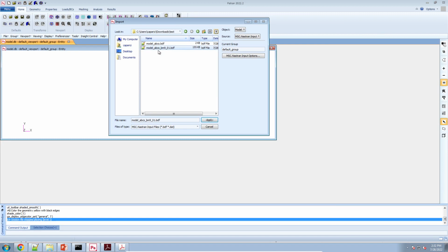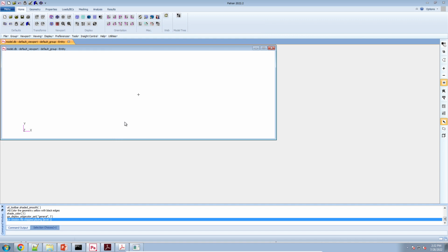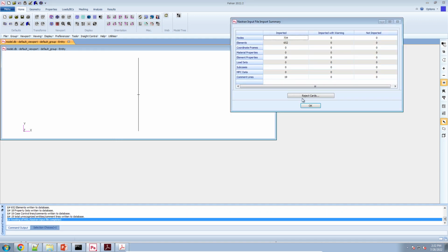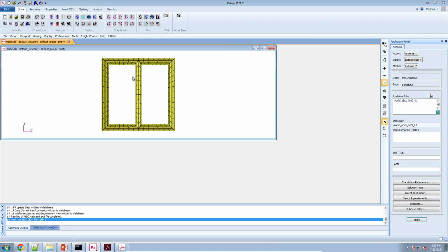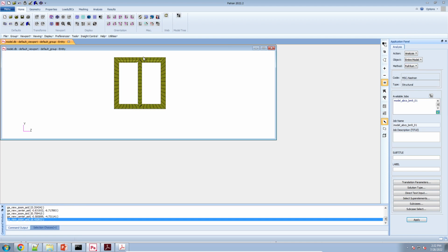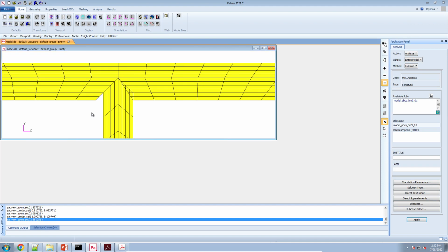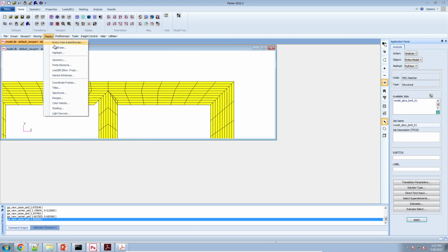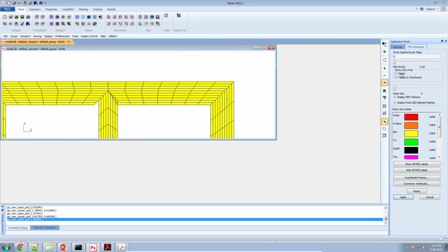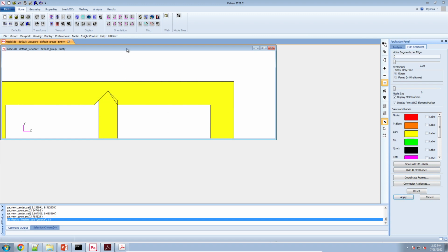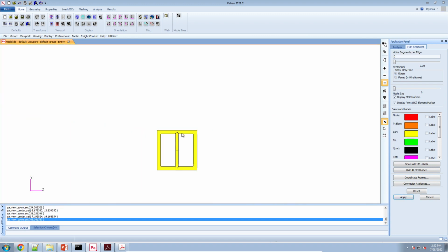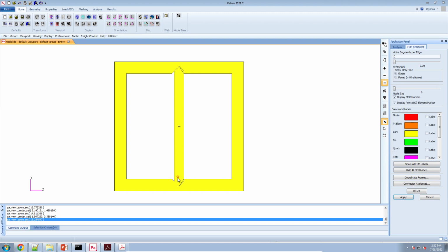So this would be model ABCS and beam 9. Let me click apply. And then if we look at the ZY view, this is what we see. The mesh doesn't look very healthy at this point. If I turn on just the free edges, you see that this cross-section, in my opinion, is not suitable. We have to somehow identify what the issue is.